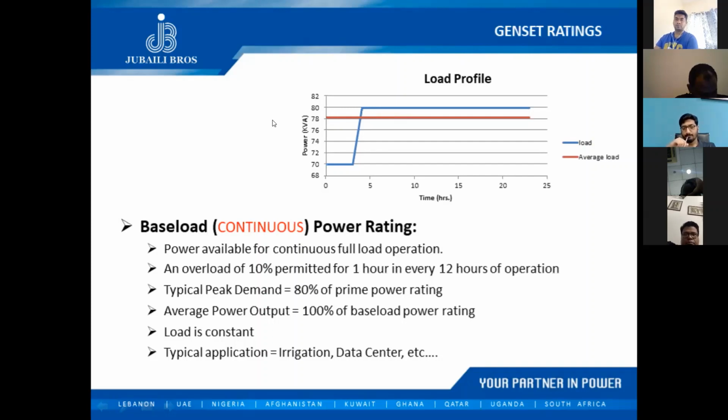We're talking about the same engine, by the way, in all of these three. We are using the generator with 70% continuous. That's even better, okay? Kabil, thanks for the note. When you consider 70% of your prime rating as your continuous rating, you're basically extending your engine's life. As simple as that. So you're giving it more room.